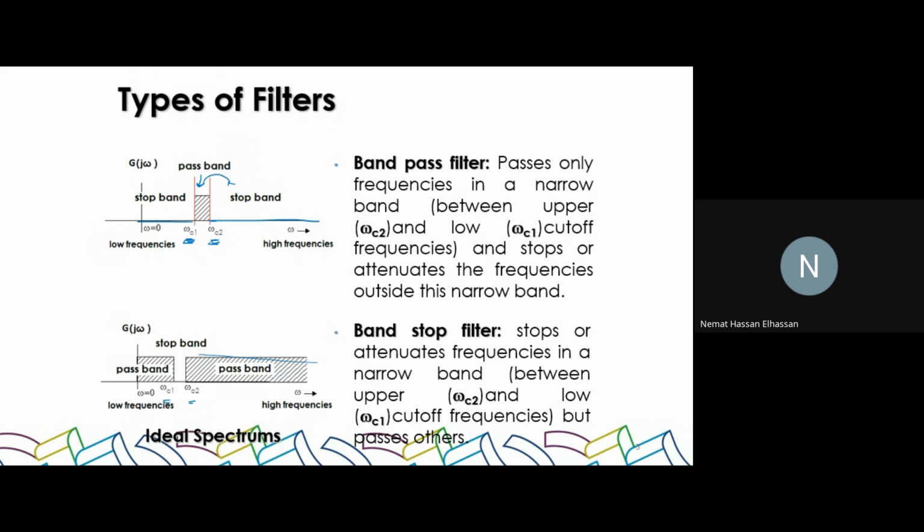An example of band stop filter is music or audio enhancement. Let's say you've recorded an audio, it's really clear, you were recording a conversation between two people, and then there was a noise, a street noise, or a barking dog, or a door opening and closing, and you want to remove that noise from your recording. So you'll choose the band stop filter to block only the frequency that you're not interested in. Make sense? So filters have a lot of these, just examples, but they have so many other applications. In communication, in system design, there are so many applications for filters in circuit design.